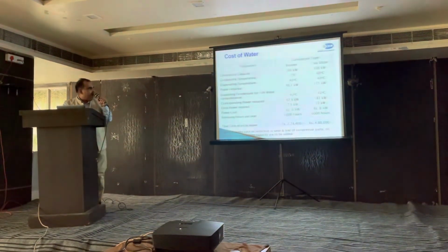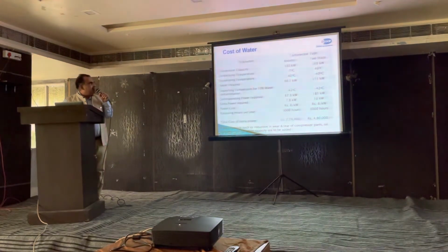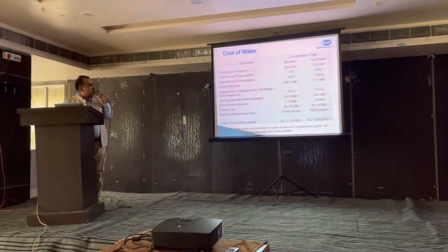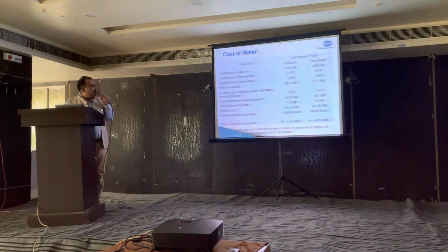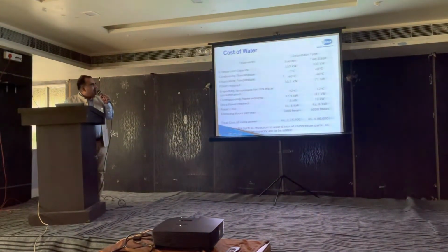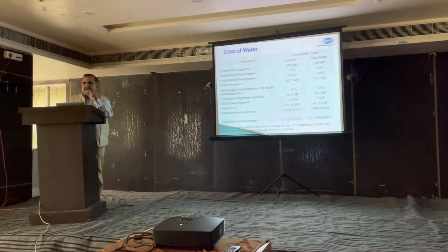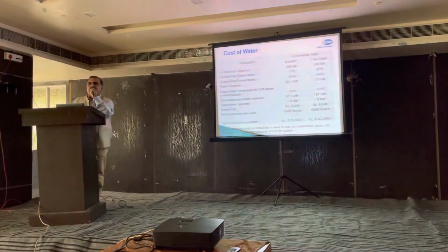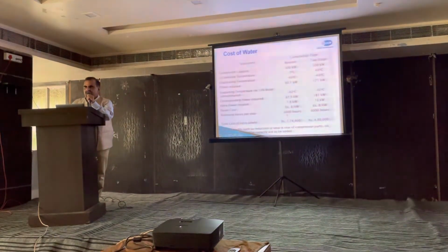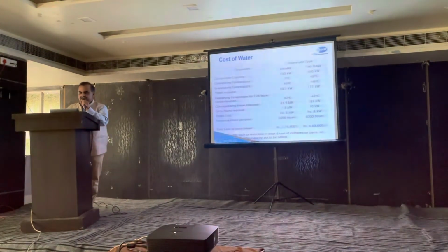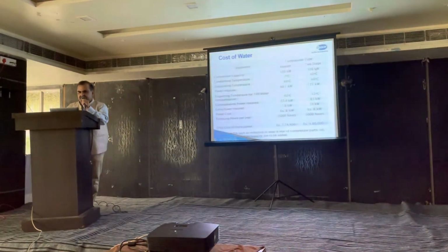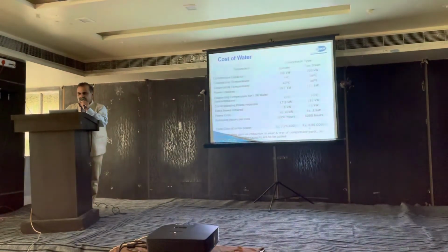Now how much power or how much wastage of water I can save. Typically for a 300 kilowatt booster compressor on the low side with minus 40 evaporating and minus 7 condensing, instead of operating at minus 40, we are operating at minus 42. Then we are talking about a saving of rupees 7,75,000 in a year when the power cost is around 8 rupees. If your power cost is more, naturally your saving will be more. And if you are having a similar two-stage compound refrigeration system, then you will save around 4,80,000 rupees.